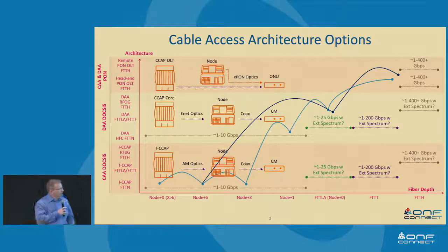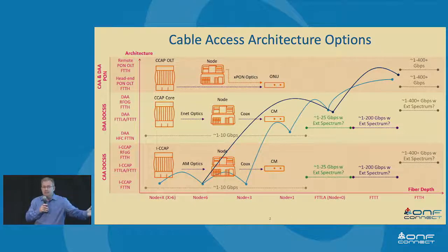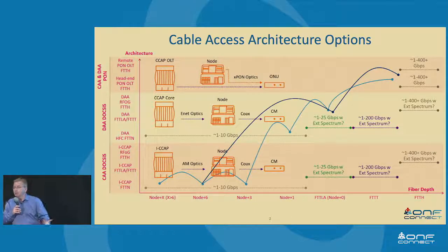And I think Alad also mentioned that today, the distribution goes out maybe 10, 30 kilometers out to a node device, right? So this is an active device. It's in the network. And how it gets there is there's an analog laser, right? Forward and return, or downstream and upstream, that's bringing that signal out to that active node element. That device will reverse that process, right? It'll take the optical, put it back into electrical, and then eventually goes down the line and into your home as a coax connector. And so that's how delivery, fundamentally, of voice, video, and data in a cable operator system will work today at a very, very high level.